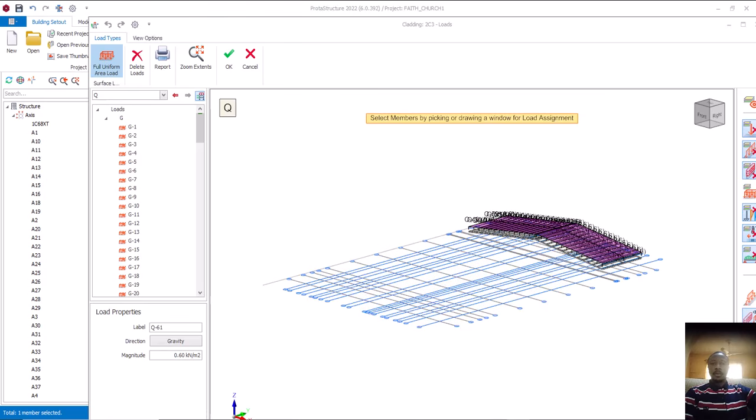And once you have kept it, you now look at the accessories. Are you hearing me? Your accessories, which is 0.15. So you now add it to it. That gives you the total load of your ceiling. Is that okay? Once you have gotten that, you also add it to the dead load of the roofing sheet itself. The process we have followed now is what we are going to follow to the end. Is that okay? All right, that is fine.